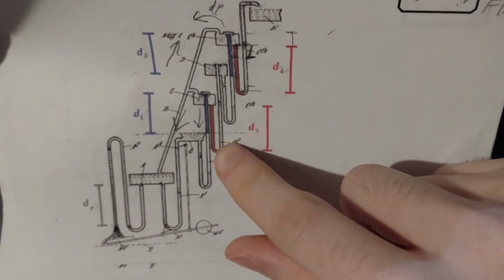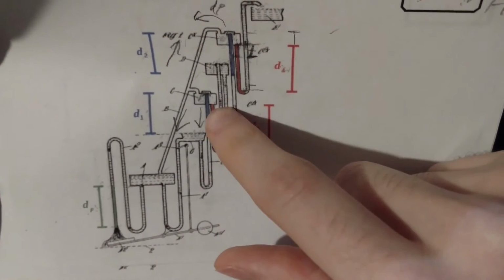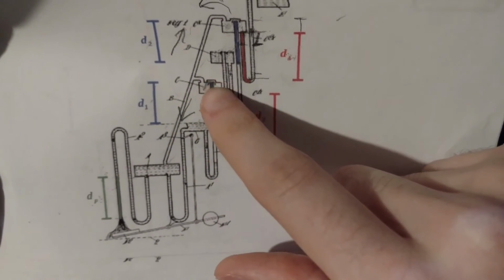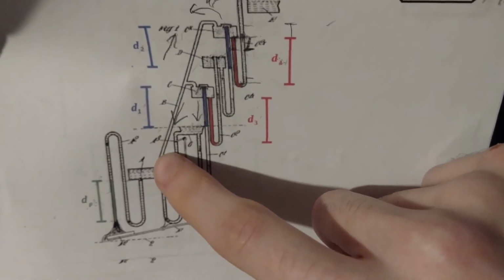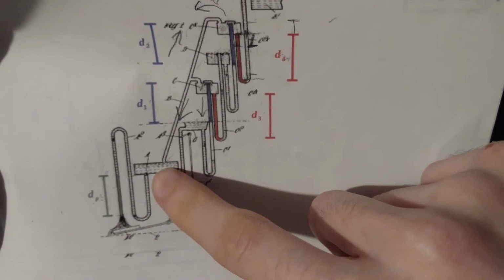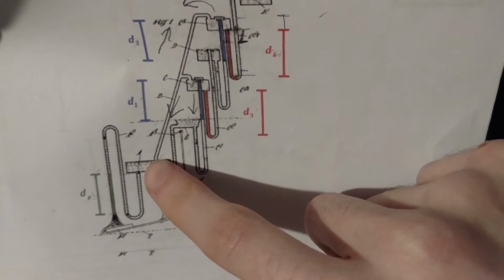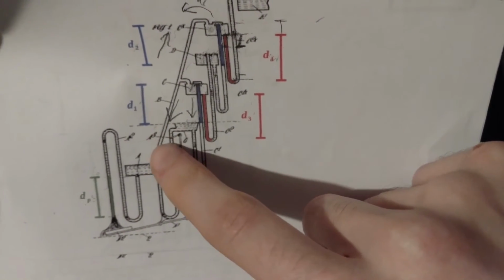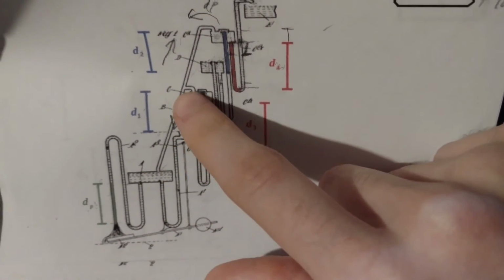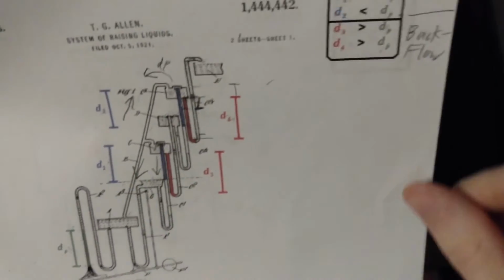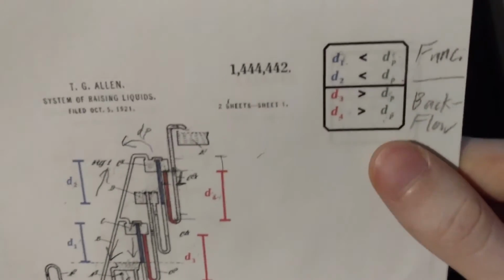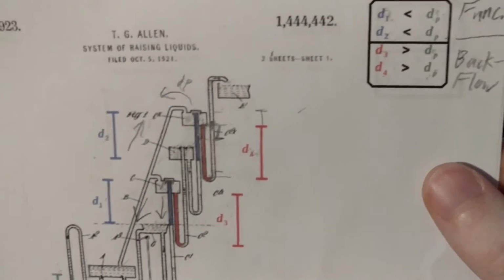But because you have a seal technically with these two closed tanks, usually what happens is you get an equilibrium before the water can reach that level. So usually the operating tank will fill up somewhere in this section here between the top of that operating tank and the water line. It'll stabilize somewhere around here, depending on what your dimensions are. It's all pressures. Everything here is just relative pressures.